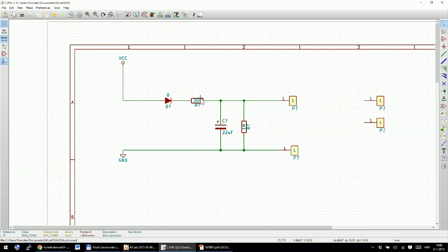So in that case, if you have like hundreds of different wires and different nets and a lot of components, if you put everything and connect each and every pin by wire, it can get very confusing extremely fast, and you will get a spaghetti schematic, which will be very hard to read, especially after a while, if you drew it and didn't look at it for a few months. So what will I do here? I will connect two virtual wires to these two connectors, and then tell Kicad that these two wires should be connected to VCC and to your ground.